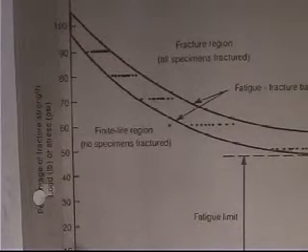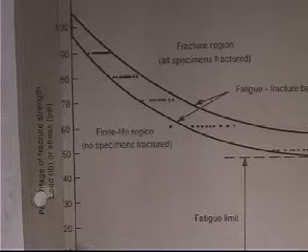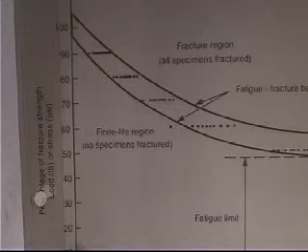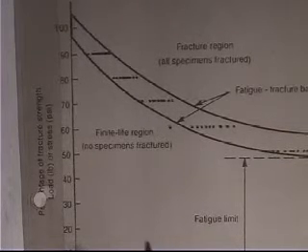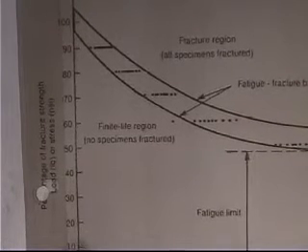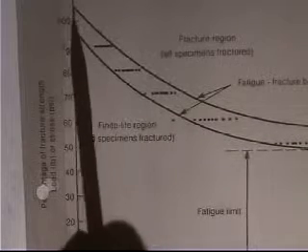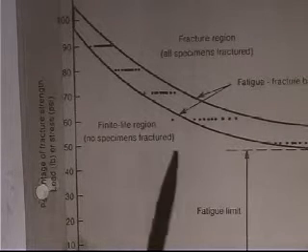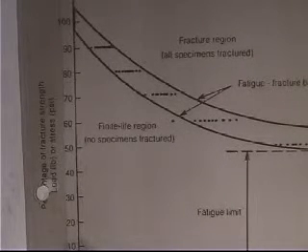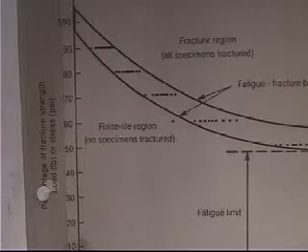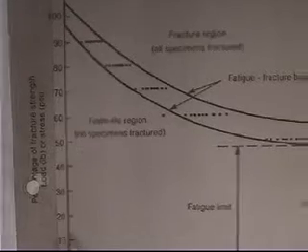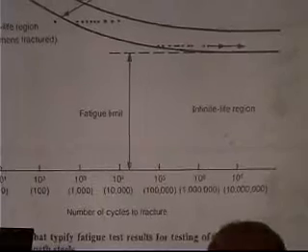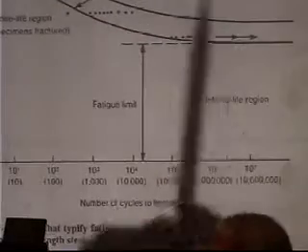Well, if you take a paper clip and you just vibrate it, or if you bend it back and forth, you're doing what's called low cycle fatigue. Somewhere between 10 and 100 cycles, the thing will break at a stress less than it would on a single cycle. And if you go out and you actually set up a machine and you vibrate that thing 100,000 times or 1,000,000 times, it will break at a still lower stress. And the curve typically comes down and then runs across fairly flat.